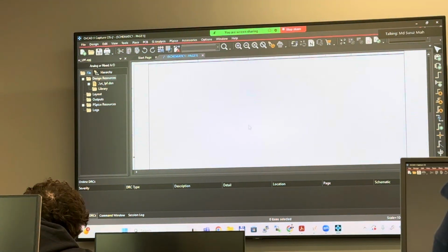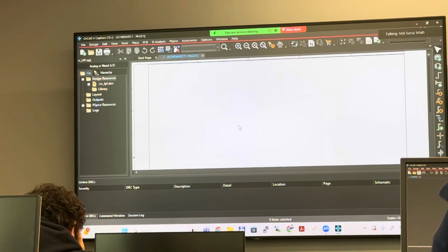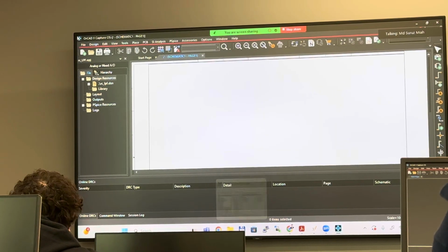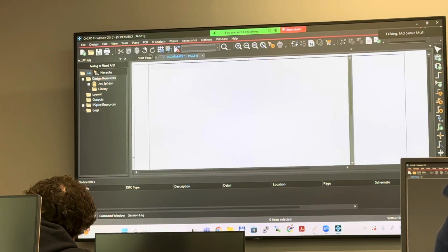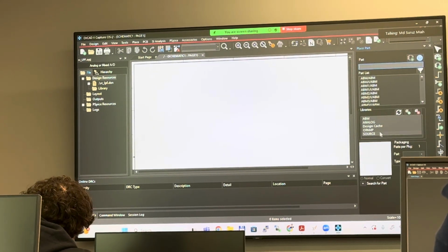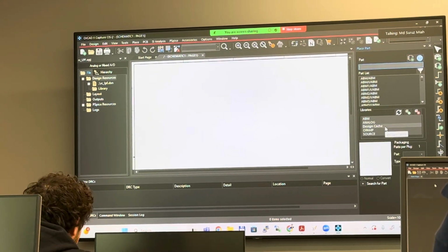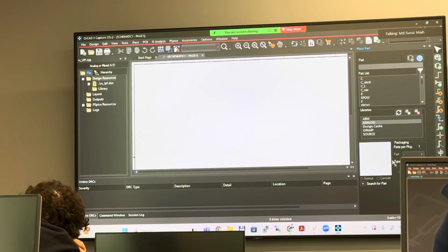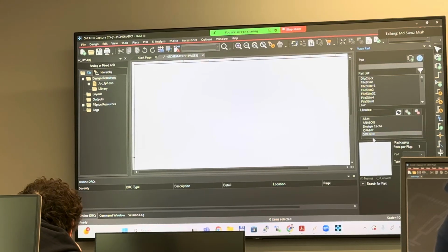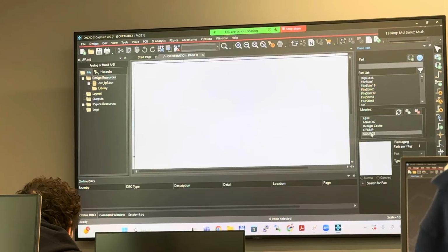This is where we will be drawing our circuit. So for that, we are going to place parts. Now we have a bunch of libraries. RC, resistance and capacitance, are in analog libraries, and source, sinusoidal source, sinusoidal signal. All the voltage sources would be under the source library. So these are libraries. Here, the list of parts.